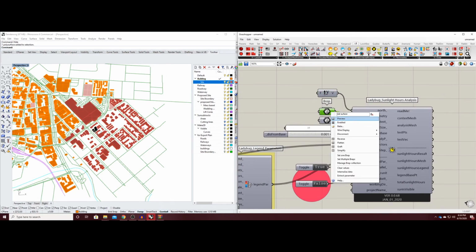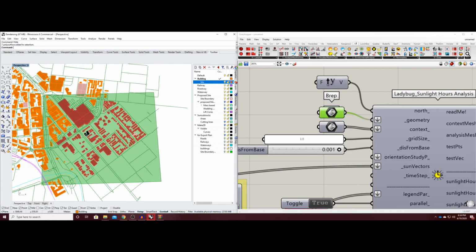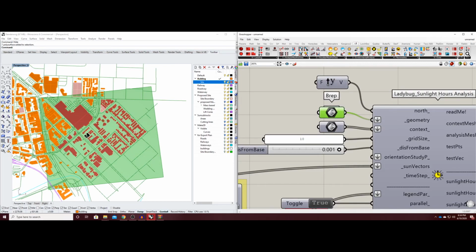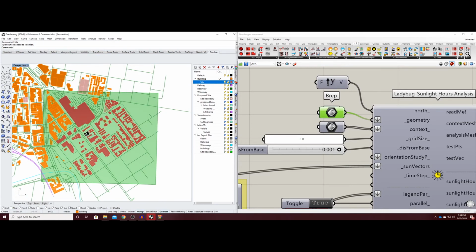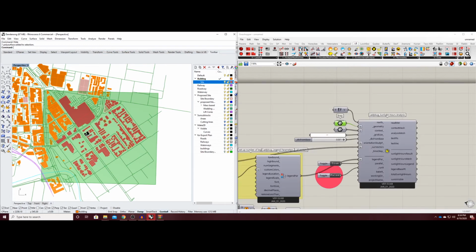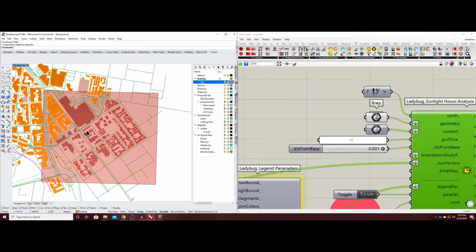So how do we do this? Just have a look at this first, because you need to make this geometry in the XY axis. If you rotate this geometry, the simulation is not going to work, so you need the plane or any surfaces in the X and Y axis, just to make sure the mesh is perpendicular to the original coordinate system.